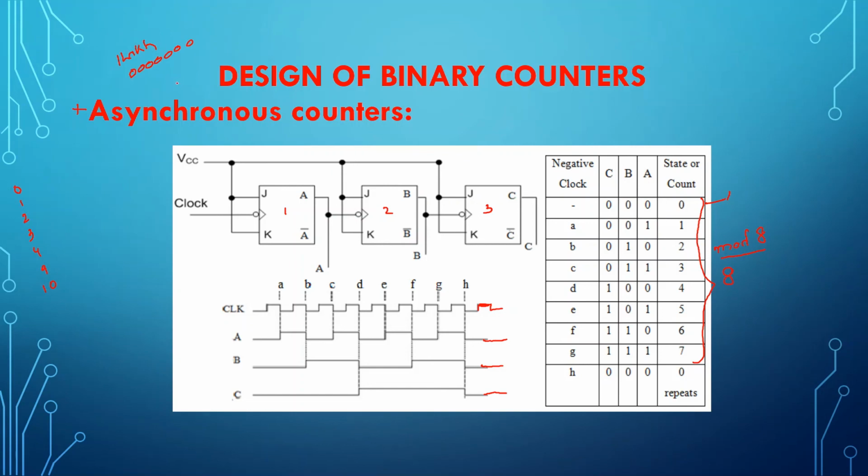The same thing. And the count that is happening here is going in the upward fashion, right? So you can call it an asynchronous up counter because it's counting in the upward fashion. And this is a timing diagram. This is a sample circuit diagram, not the exact circuit diagram. Circuit diagram we'll check out later. Normally, in the case of counters which you have designed using flip-flops, the complemented or inverted output is not considered. It is not considered until and unless my design demands it. If my design says that I want that output, we will study that in the upcoming sessions.